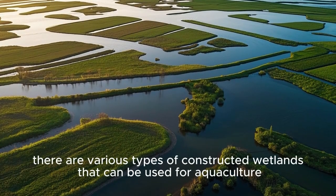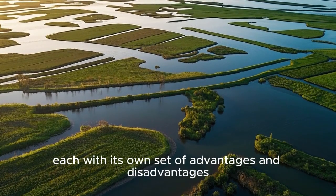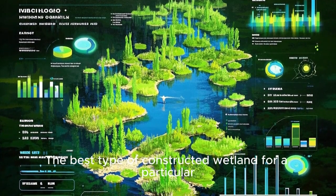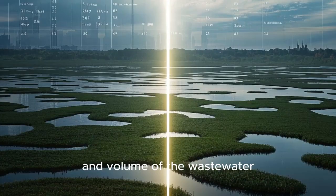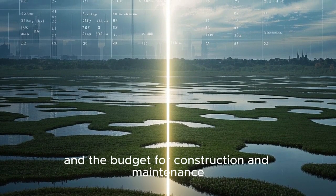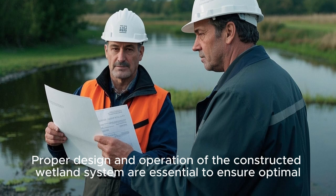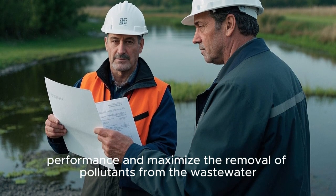In conclusion, there are various types of constructed wetlands that can be used for aquaculture, each with its own set of advantages and disadvantages. The best type of constructed wetland for a particular aquaculture operation will depend on factors such as the strength and volume of the wastewater, the available land area, and the budget for construction and maintenance. Proper design and operation of the constructed wetland system are essential to ensure optimal performance and maximize the removal of pollutants from the wastewater.